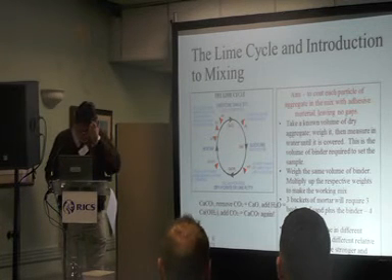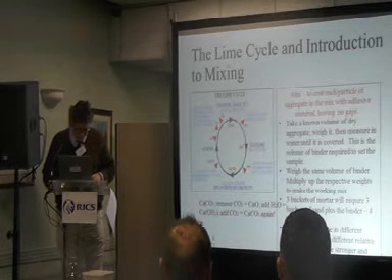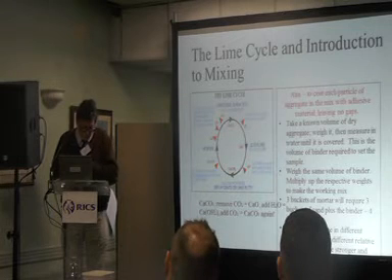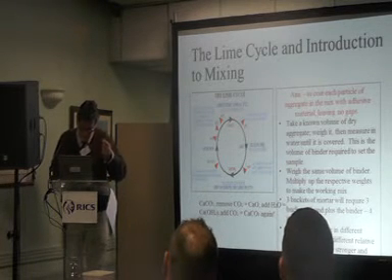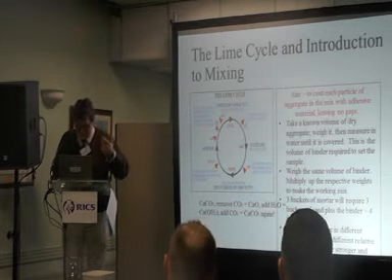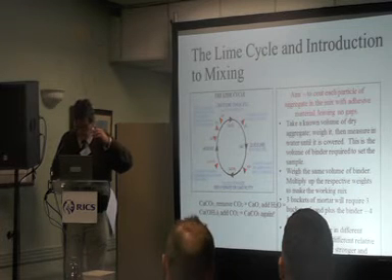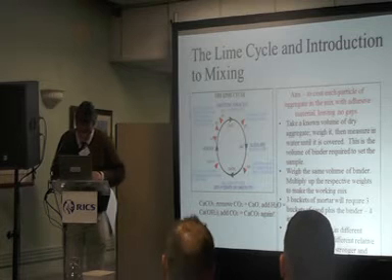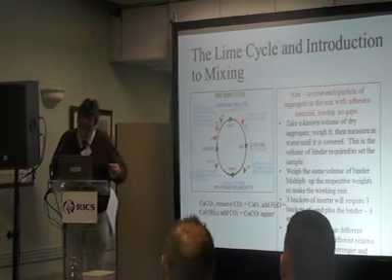Now, NHL hydrated lime comes in different strengths and with different relative bulk densities, so don't just use 3 buckets and 1 bucket. And use the stronger, denser limes as base coats, and in the more exposed work, so chimneys and things, where frankly you're not going to get up and do little bits and let it dry carefully. You've really got to let it go off. So use a stronger binder and a stronger mix. It's really worth learning more about lime and using it more.